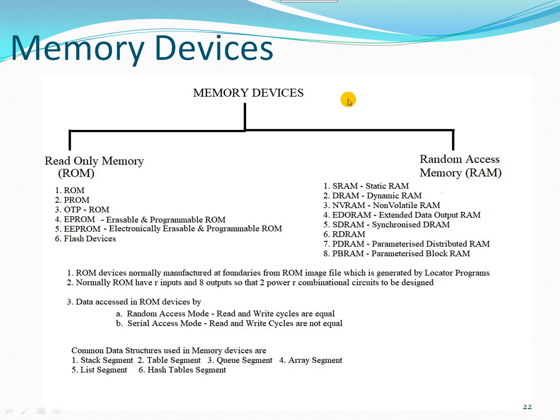So what do you mean by a ROM image? Whenever we have our program to be executed, that program has to be converted into a hexadecimal file, because a hexadecimal file is eventually a binary file. We need to convert the programs which we have written in our high level languages with the help of tool chains. Tool chains means compilers, assemblers, linkers and locators.